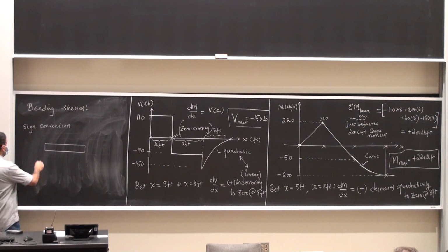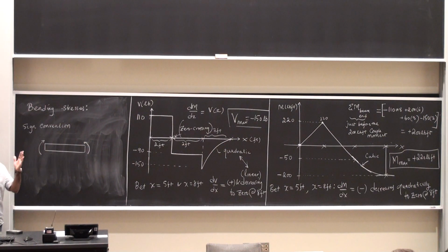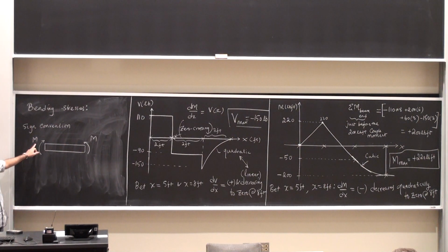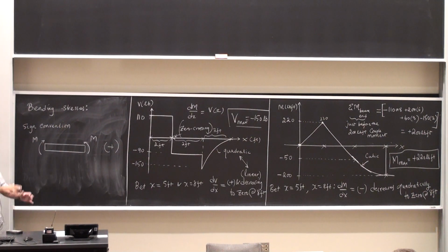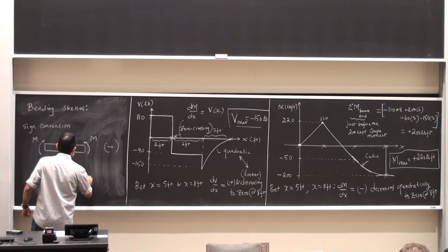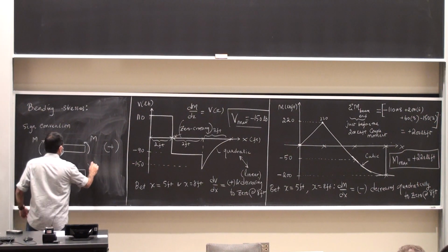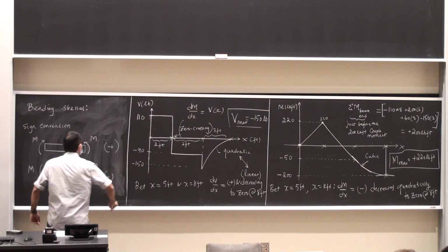If I look at a beam and cut it, and this is the direction of the bending moment, then this is concave upwards, the positive sign convention. So in this case, M is positive. Obviously, the inversion of that is my negative sign convention. If I have a situation of this sort, then the value of the bending moment is negative M.